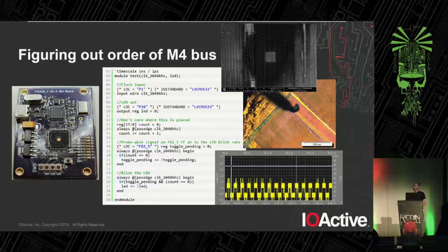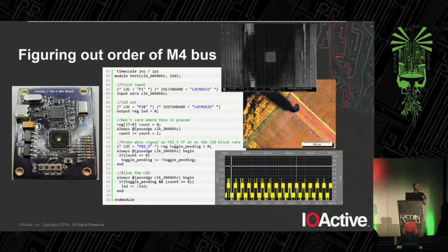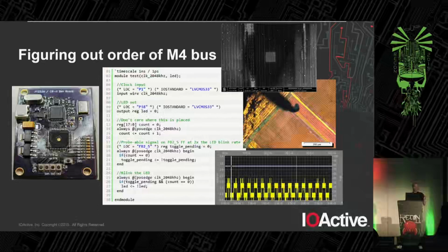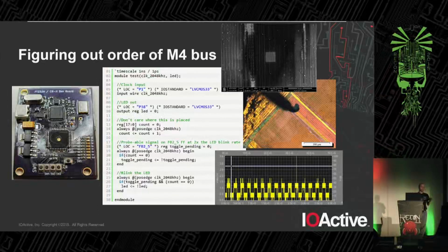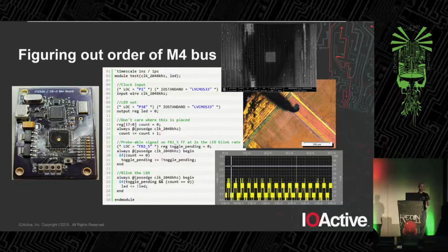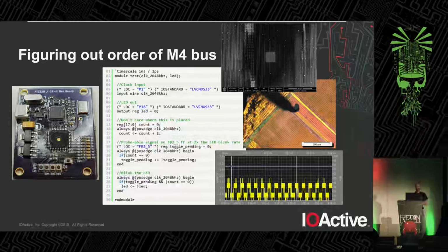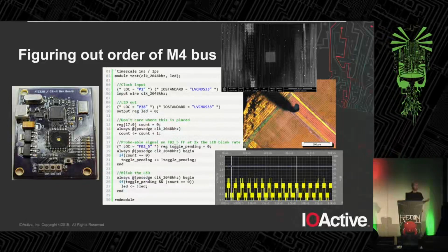There were a couple of options I considered, but it turned out that one of the simplest was to make a few educated guesses about how things were structured. So, for example, all of the macro cells in function block 1, their flip-flops are probably in a contiguous order in the bus. We don't know where in the bus they are, but they're probably contiguous. All of the input pins for function block 2 are probably contiguous as well. So let's tinker around a little bit.